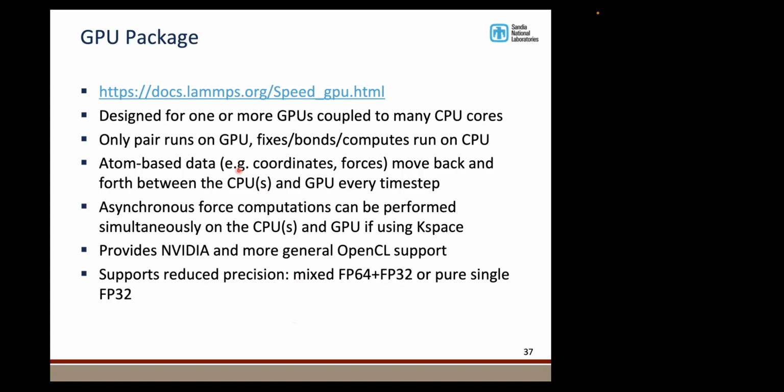I'm not sure about the Sphere package, but for all of these accelerator packages, only a portion of LAMMPS has been ported. So the first thing to do would be to check whether the styles, like the pair style and the fixes, are ported to the GPU package. Otherwise, it's probably not worth running the accelerator package, because you're just going to fall back to the vanilla code anyway, and there could be overheads. So that's the first thing. I don't think there's any acceleration of the Sphere package, but I'm not sure. I'd have to check.